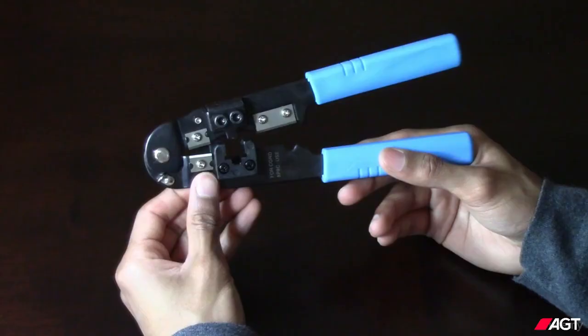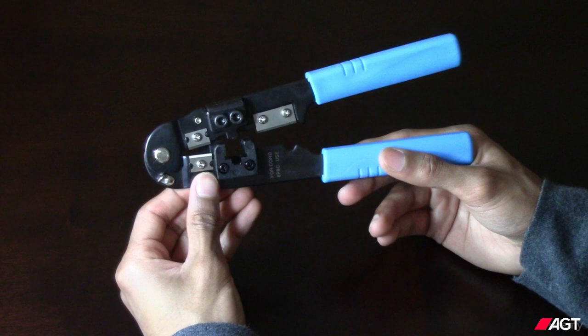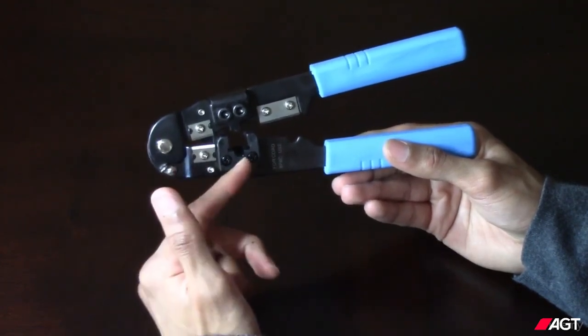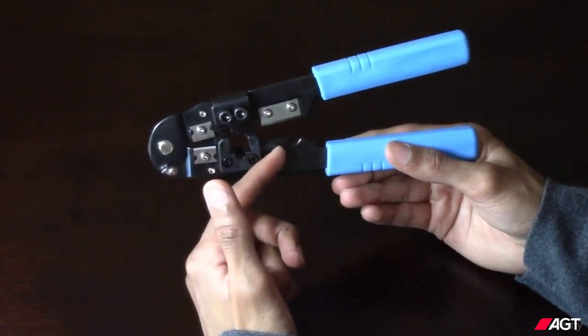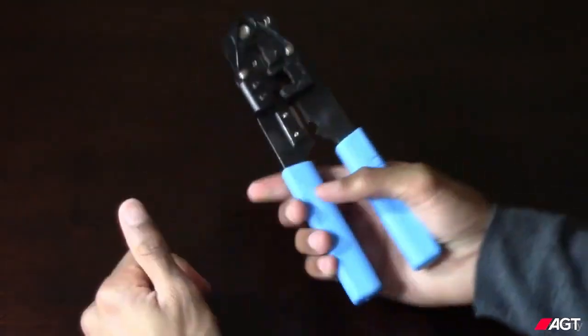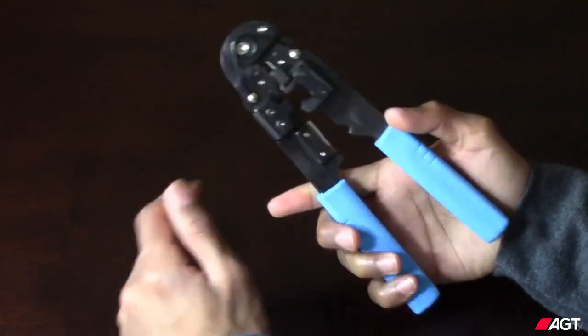So the first thing we're going to take a look at is this thing called the crimper tool. It has a few main functions, the main being that it crimps an RJ45 connector securely to a cable. You'll see that it has a pair of blades up here, the crimper section where you insert the connector, and another pair of blades down here. These blades are used to cut wires evenly, which is kind of hard to do with scissors. It's a fairly simple device. You just squeeze it to crimp your tools or cut wires.